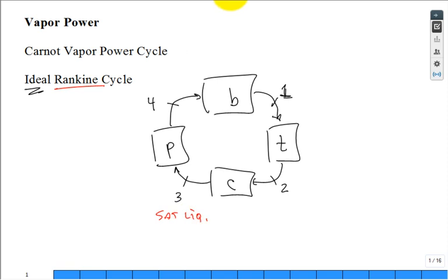All right, we bring in all our heat into the working fluid. And for the Carnot, all of QH, or QB, comes in at a temperature TH. All right. Likewise, in the condenser, I'm going to show it this way. QC is coming out. I know sometimes I have a negative sign on it. You just have to watch your signs. But it's rejected, and that's all rejected at the fluid at TL. Right? All right. Okay.